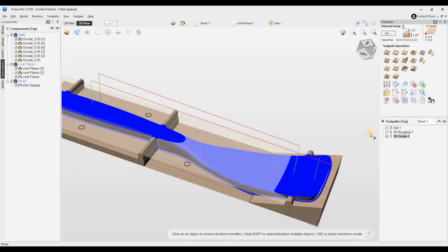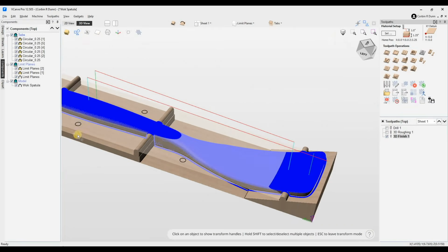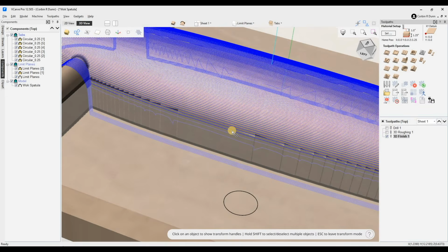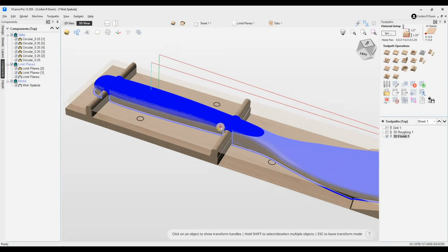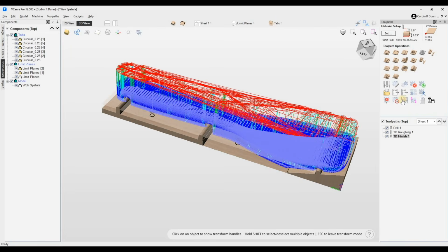Okay, it did something. Let's see what kind of toolpath it generated. A lot of roughness on the side here. This is one of the problems, these jagged toolpaths, one of the problems of Vectric VCarve and the way it generates toolpaths and imports models. I haven't really figured out a way around this issue. That looks like it will machine it correctly.